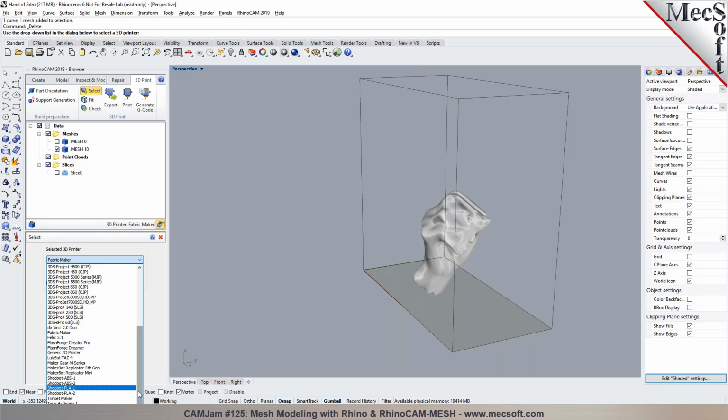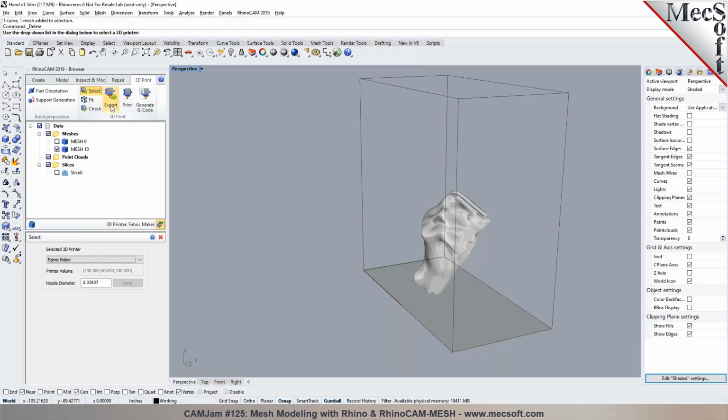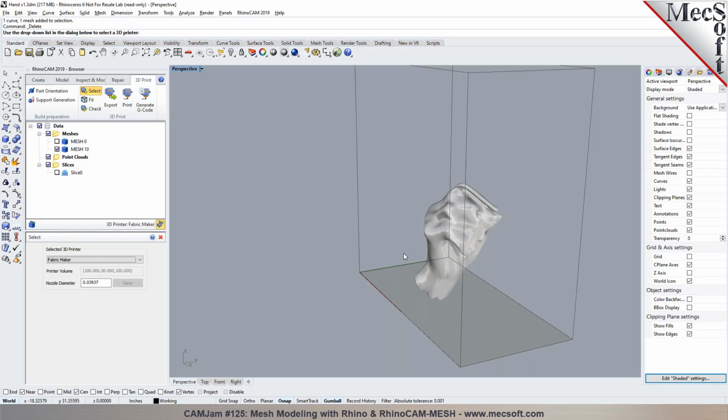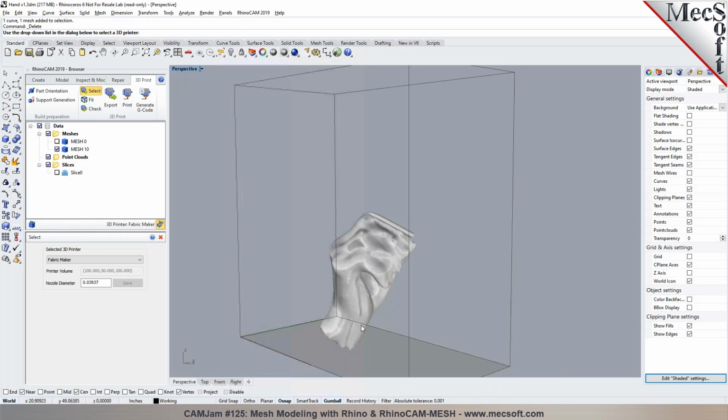If you want to do G code, we can do G code, or we can do STL output. And you can also STL output it. Yep. And how are you doing that? Are you doing that just as in a save as command, or is that within RhinoCAM? We do an export right here. It'll convert it, drop up a STL or SLA or AMF format. Okay. If you want to do supports, you can do supports in here.